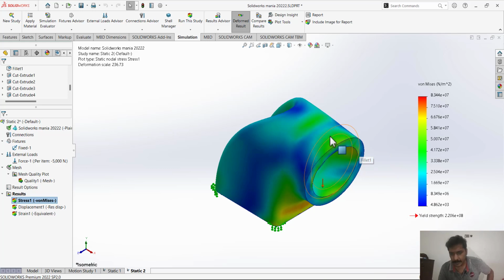So if I am a design engineer, I can make a decision for this component. We can reduce the thickness, or make the length or the height a little bit smaller, so we have less material and we save cost. Basically, we do this analysis so we can save some material, or if the design is failing, we have to add material.